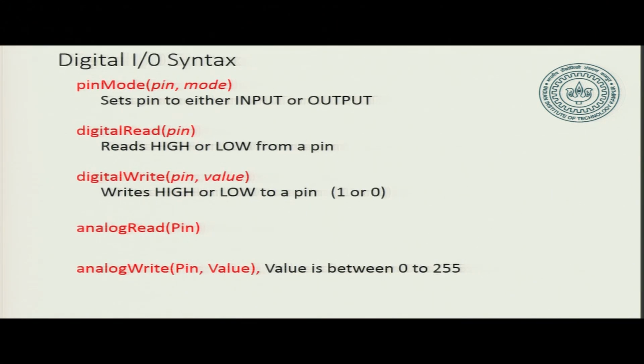Now, what is the syntax? The syntax is very simple. So, pin mode is set up by this command. Now, you'll see something which is very interesting here, that the language is English like. If you just read it, you understand that it is an English like command. Pin mode essentially in English means what is the mode of the pin, and it simply says pinMode. So, pinMode first takes the pin number. So, we are going to give a number here. What is the pin number and what is the mode? Is it an input mode or an output mode? Okay. So, it is a very simple command.